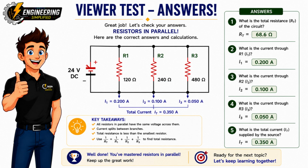For R2, it's 0.100 amps. And for R3, it's 0.050 amps. Finally, to find the total current supplied by the source, we simply add the 3 branch currents together. 0.200 plus 0.100 plus 0.050 equals 0.350 amps.